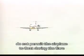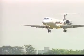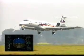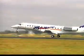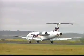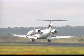Do not permit the airplane to float during the flare. Using a normal flare technique as the airplane approaches the touchdown point, reduce the rate of descent by increasing the nose-up attitude and slowly reduce engine power in order to achieve idle as the airplane touches the runway. Normally, a 2-degree or 3-degree pitch-up change is required to reduce the rate of descent during the flare.